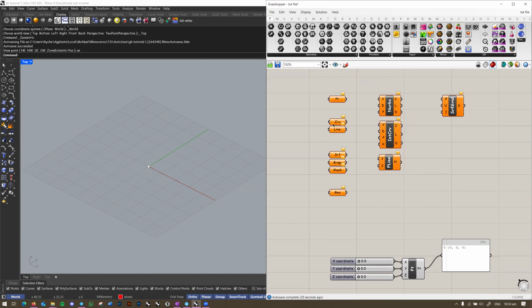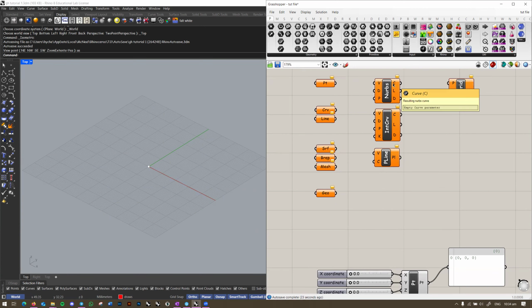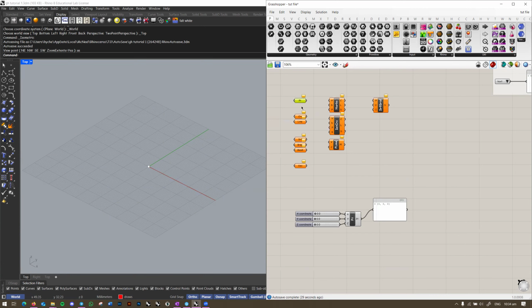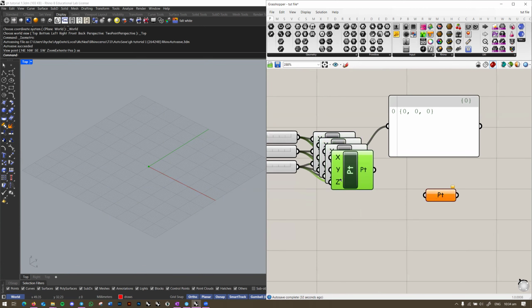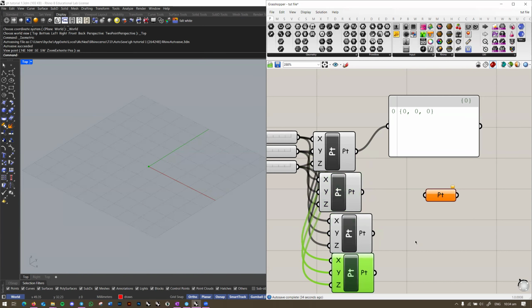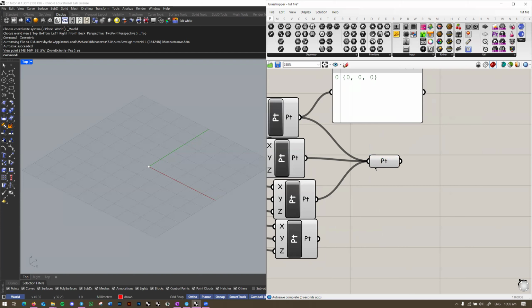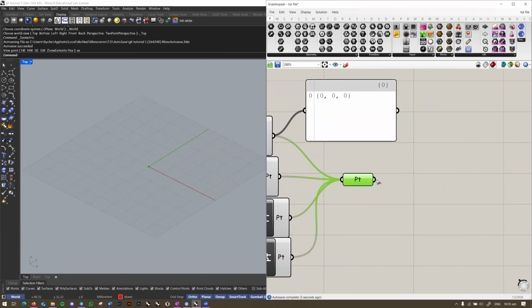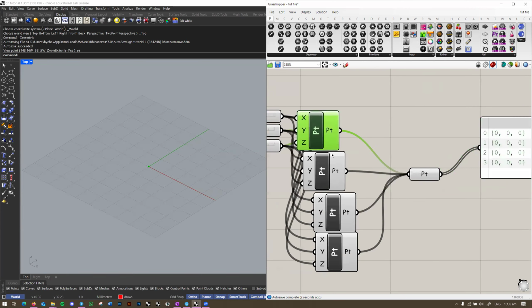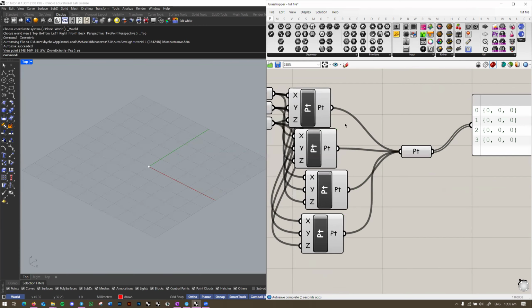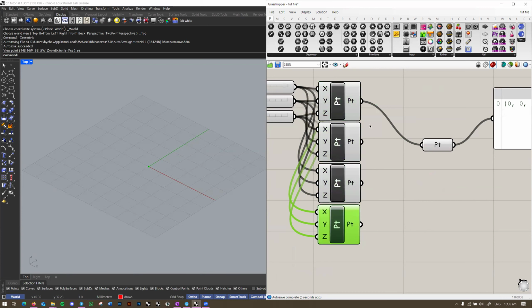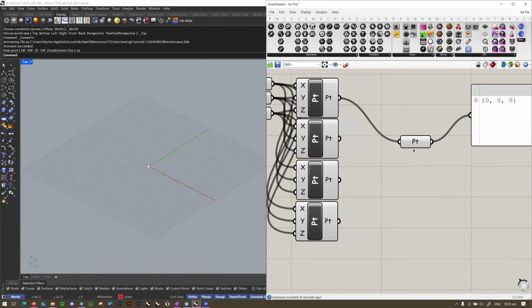So containers are good for helping you to reference items or containing a set of items. For example, I'll show you later, but if I bring over this point container and I have many, many points that I'm creating, I can put them all into the same container by holding down Shift and dragging all of them into this container. So now within this container, I have 4 points instead of just each of these individual points, right? And if I want to put a point into this container, I drag and click into here.